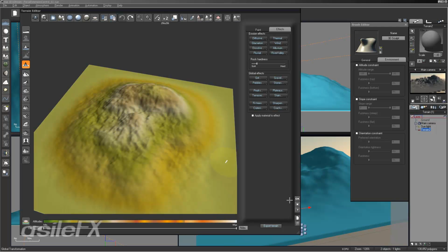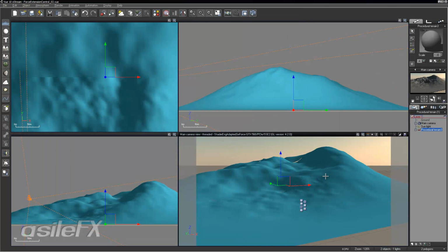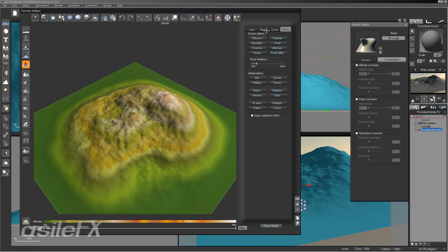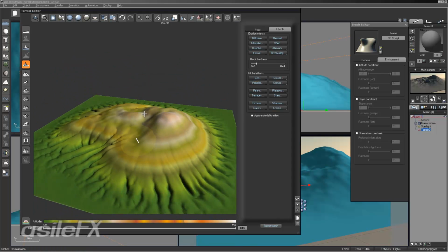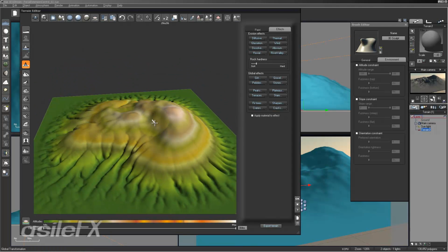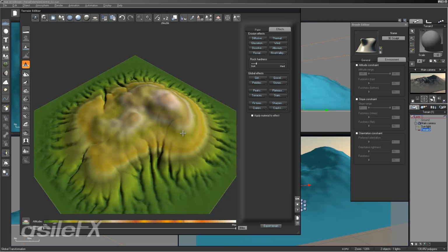So if you want a more accurate representation, I'm just going to cancel, go back into the procedural terrain, keep that force extension at 1, and then convert it to a standard terrain. And now as I start to add the effects, you can see they're applied a lot stronger and more like a standard terrain or height field terrain that you create within the editor on its own before converting it over.